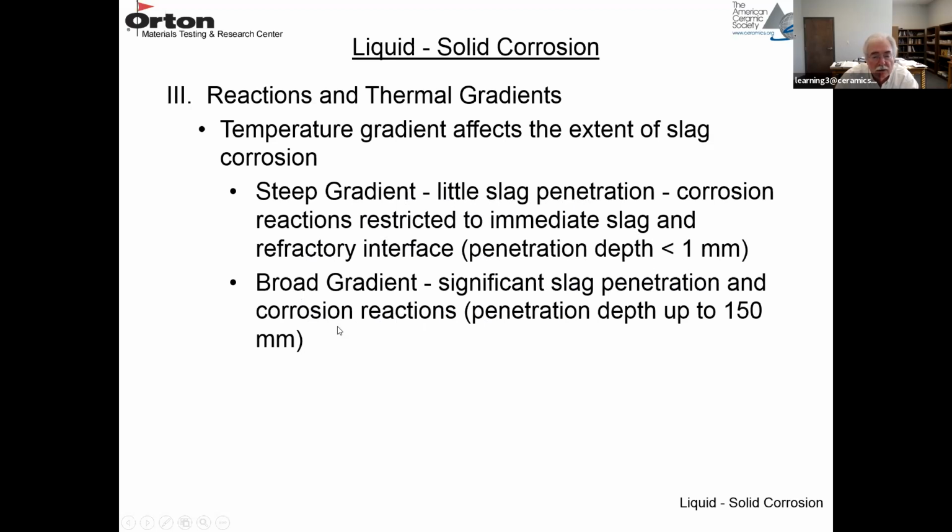If you have a broad thermal gradient, you can have significant slag penetration and materials diffusing into the refractories and causing reactions. And that penetration depth can be much larger, maybe 150 millimeters.